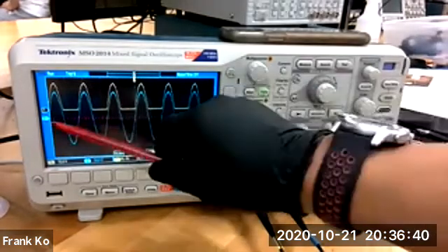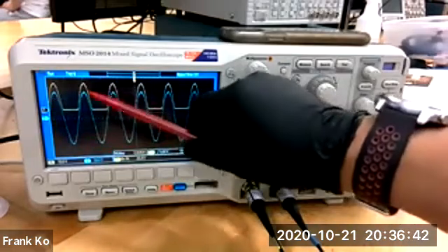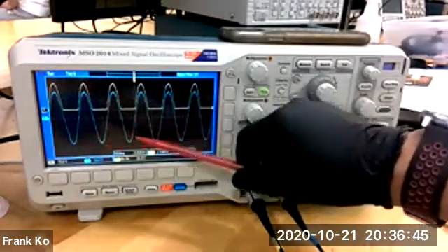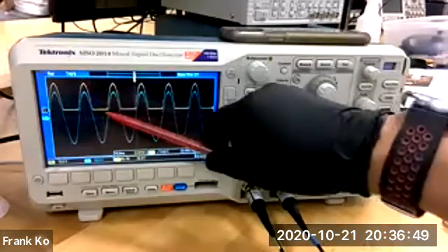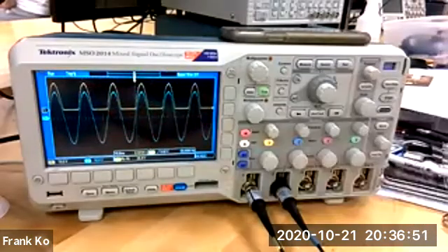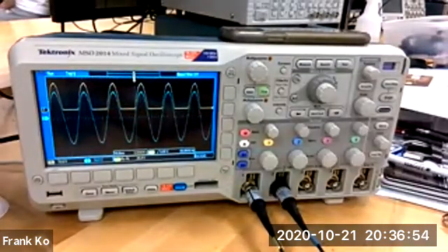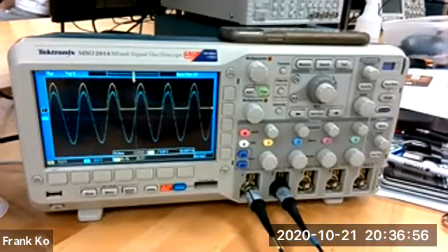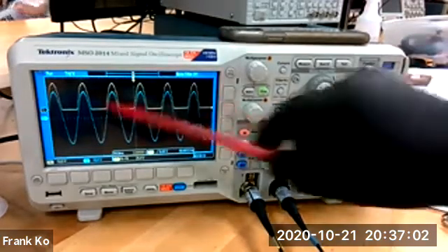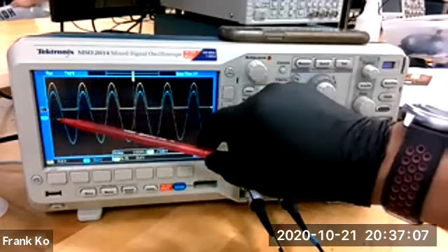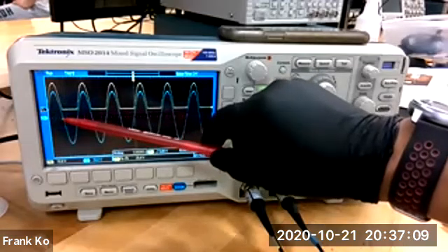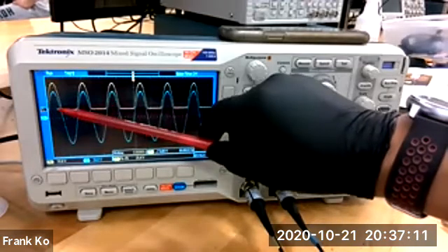Yes. The blue waveform is your input waveform, meaning before the diode. The yellow waveform is the output of the diode to the load. And this is called half wave for this reason. Eyeballs on my screen. It's half wave because we're using the positive half cycle of the blue waveform to give us a positive half cycle on the output.